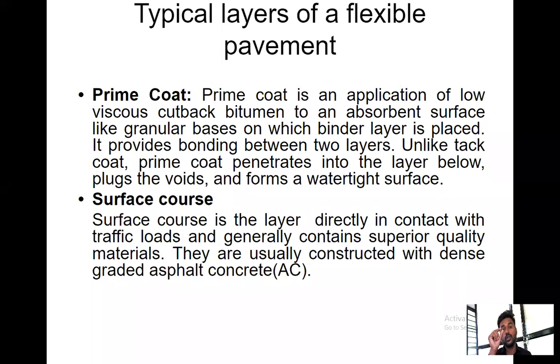The maximum stress will be there on the surface course. Because it is directly in contact with the wheel, there will be higher stress on that layer. So we need to achieve superior quality for that particular layer. The surface course should be of superior quality because it is directly connected with the tire loads.